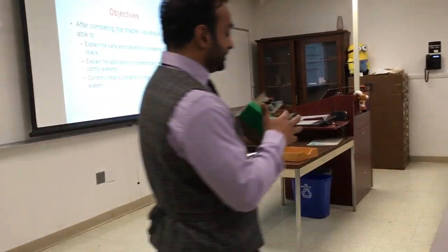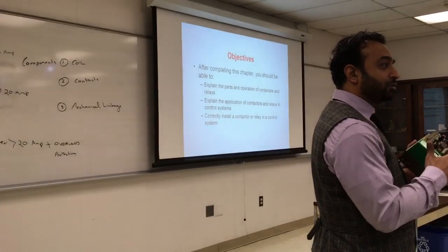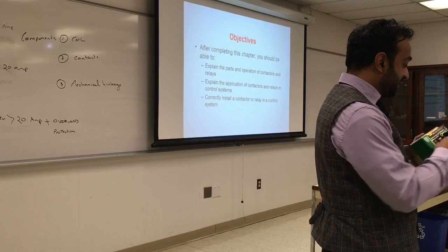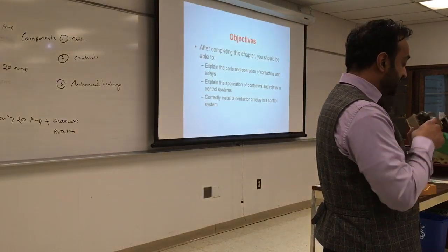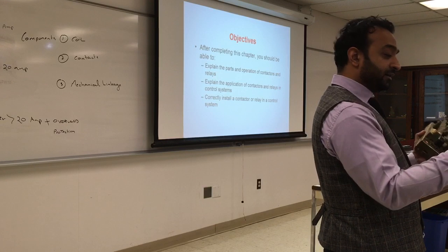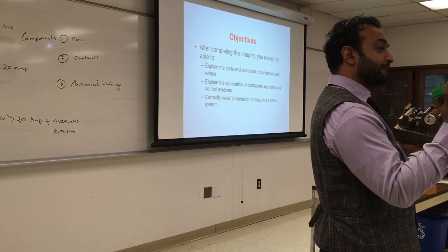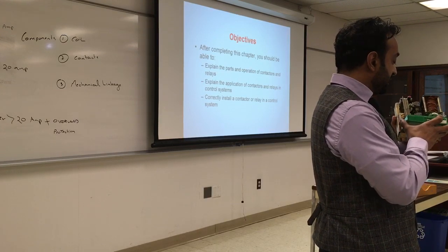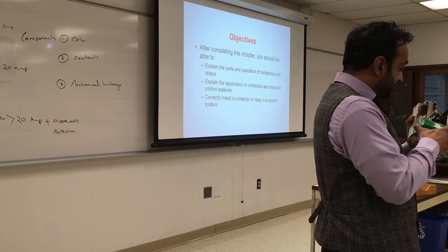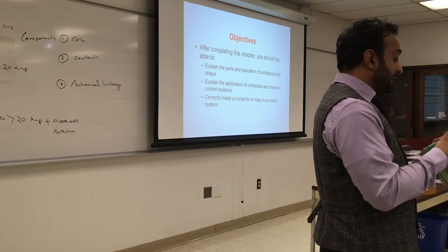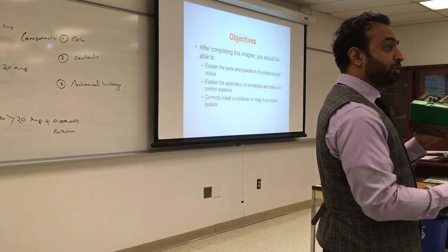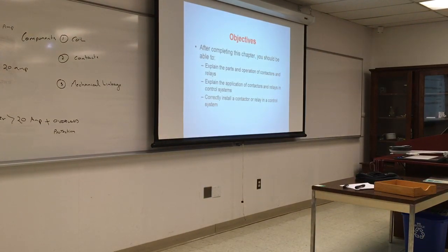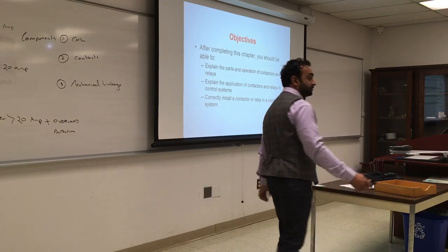So if we look at it here, this is a mechanical timer, just like a cam, and it provides the sequence of operation. We have two mechanical relays here and a transformer. This chip here can be changed; this is for the flame detection system. We'll talk about these repeatedly and a lot next semester. But if you look at the mechanism, it's very interesting. They cover the entire board, so you don't even touch them. I highly doubt you'll see these in the field, but you might come across one of those.